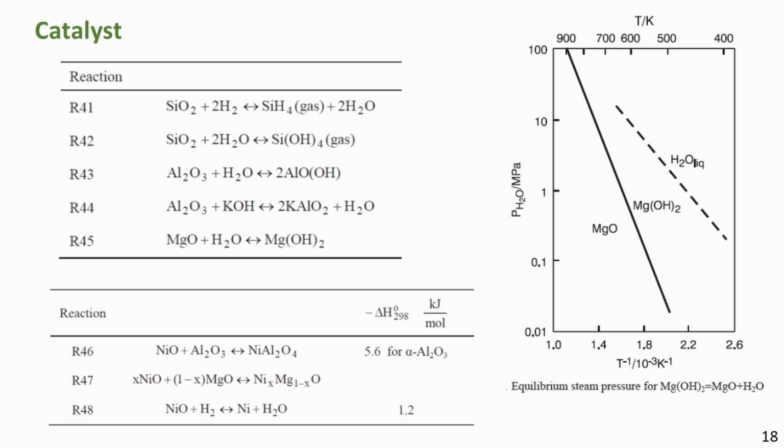The alkali loss is enhanced by high temperature, but may, to some extent, be controlled by addition of acidic components. The volatile alkali may deposit in colder parts of the plant, where the resulting hydroxyl ions will strongly promote stress corrosion in stainless steel. Moreover, alkali may react with some catalyst support materials such as alumina, forming weak aluminates, resulting in a decrease in